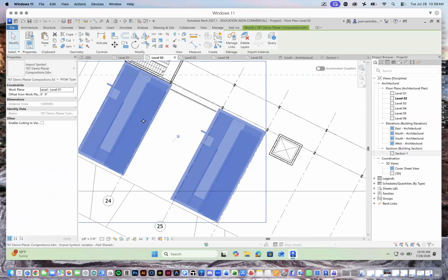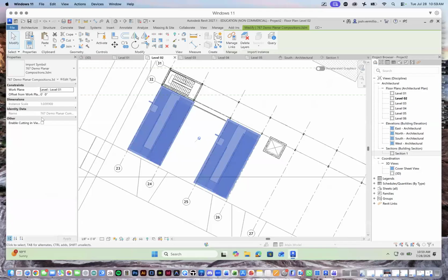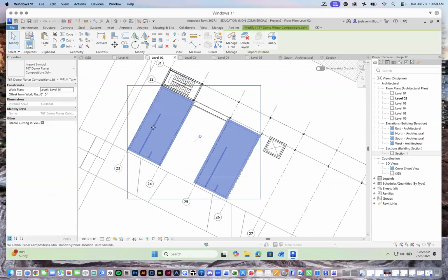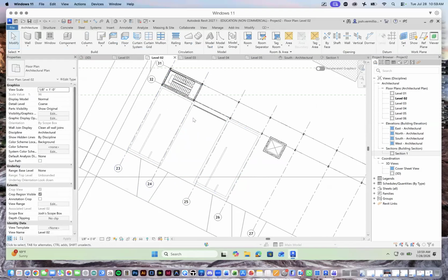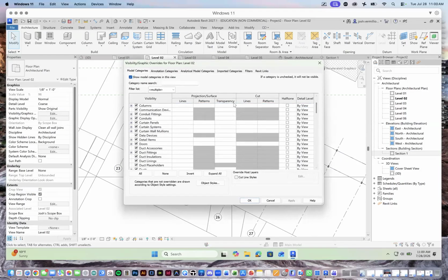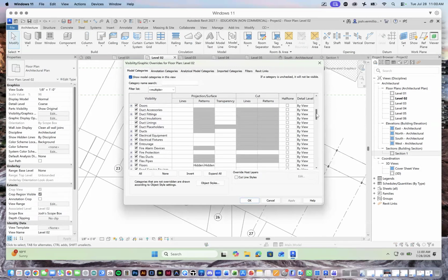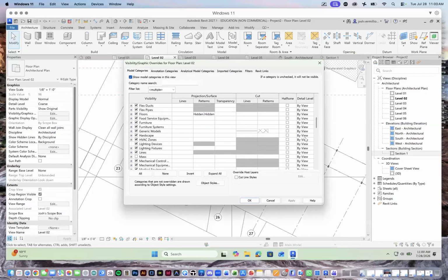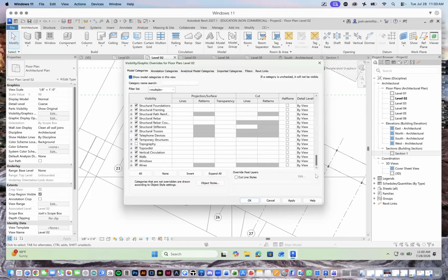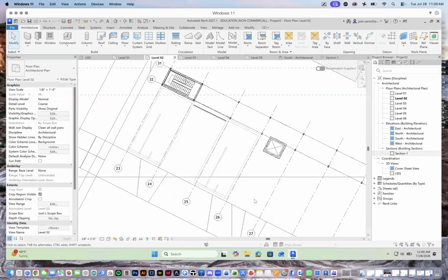This is import symbol, 3DM, enable cutting in views. Here we go. So now I've enabled the cutting in the views by selecting this and looking at its properties, each of these modules, the Rhino model, basically. And then later on in the plan, I can go to the visibility graphics and change how it's actually formatted: color, line weight, thickness, etc., and line type. I forget what they called that. But anyway, I'll look into this over the afternoon. And when I have something to show you guys about that, I can show you.